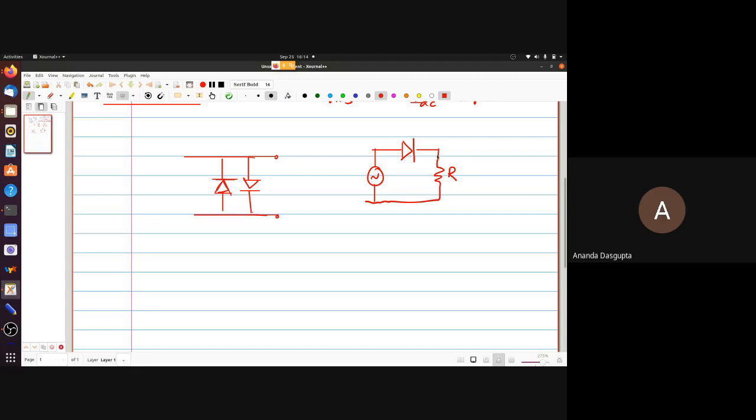Now this takes some getting used to, because although we all know this in theory, very often people get confused: how come no current means high voltage? But you have to remember, no current means no current through the resistance, hence no drop there, so high voltage across the diode. Fine. But that is the ideal case. Ideal case means no drop whatsoever in the forward direction.